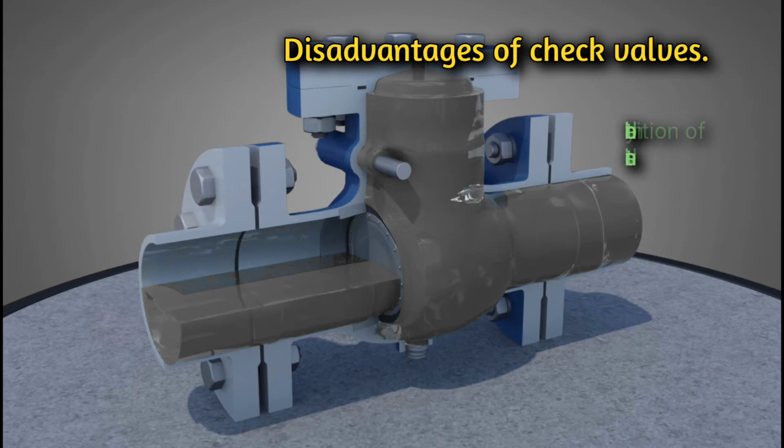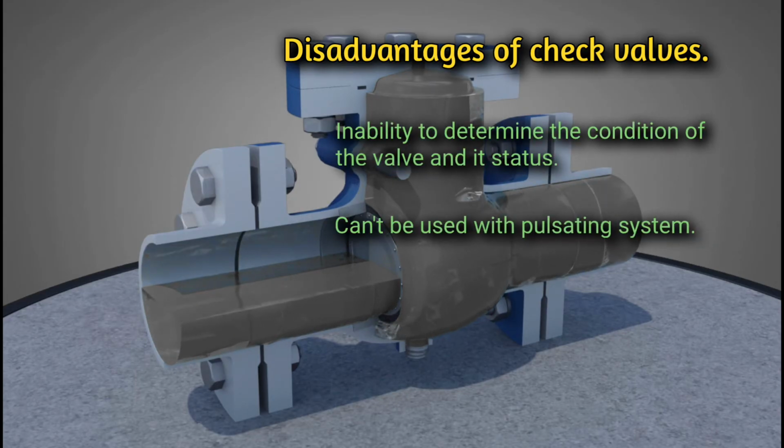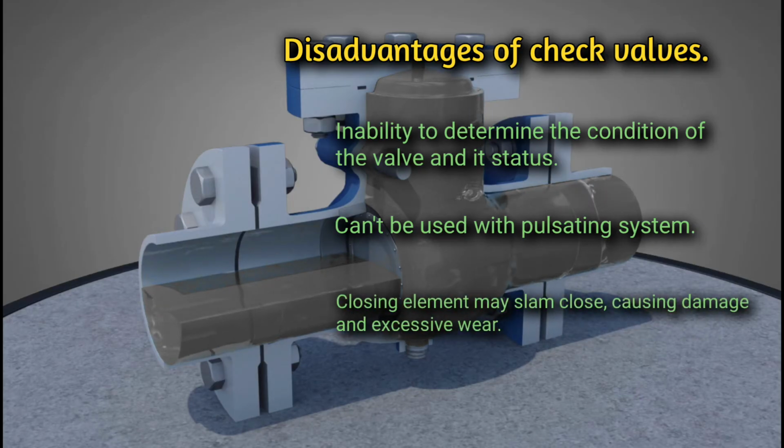Disadvantages of check valves. Inability to determine the condition of the valve and its status. Can't be used with pulsating systems. The closing element may slam closed, causing damage and excessive wear.